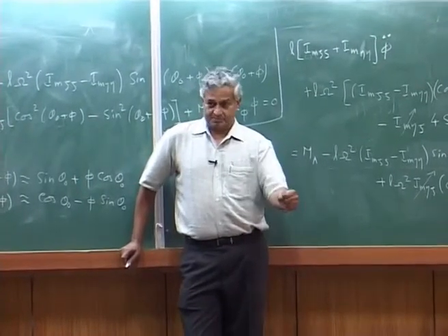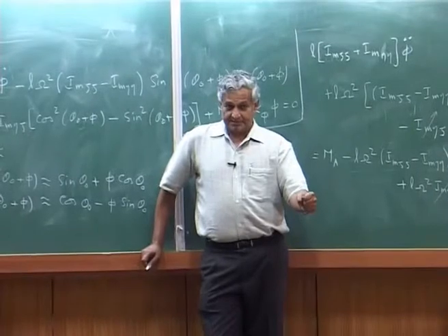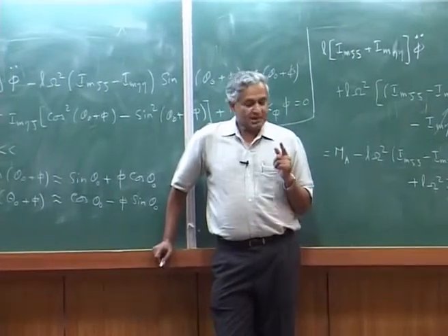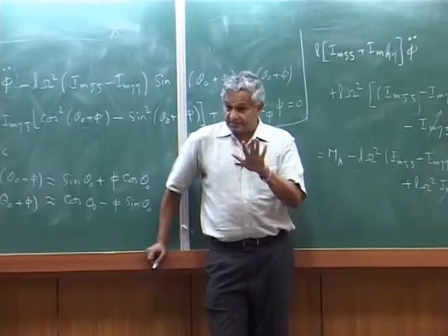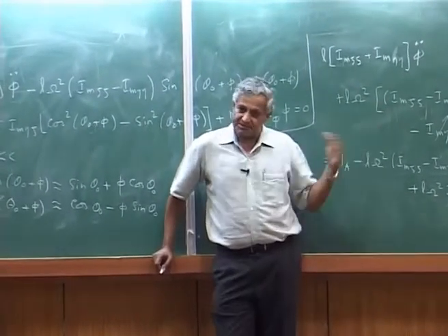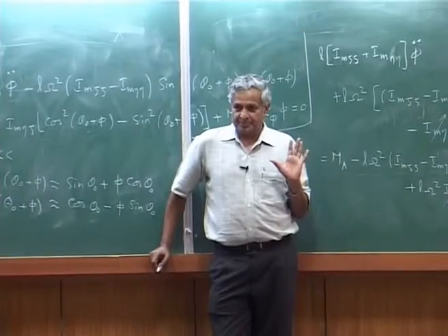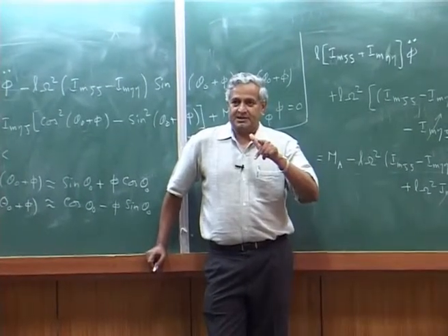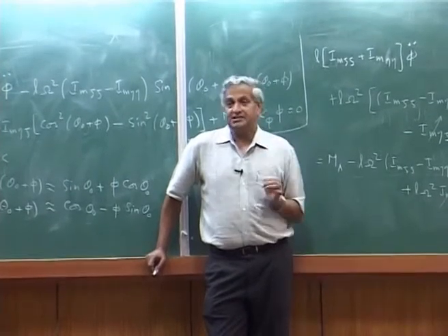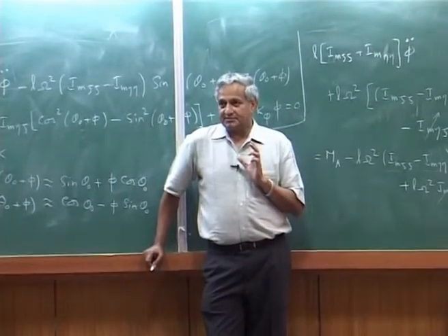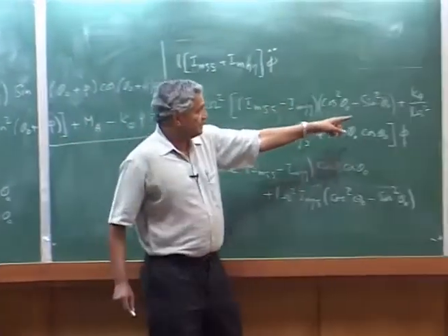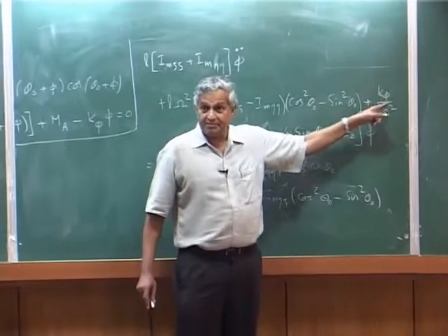This is my pitch angle. But what the blade experiences is not the same. Just dynamics, no aerodynamics. When aerodynamics comes, that will also change the angle of attack. But here, because of the elastic twist, you will find a loss in the pitch angle. That is due to the Kphi. Kphi plays a major role.